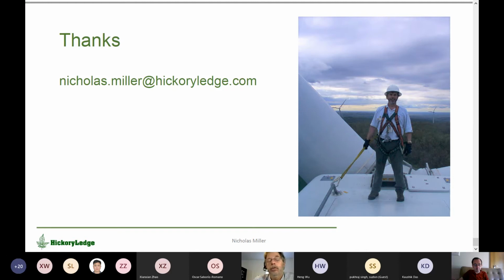So you can ask all sorts of questions, like, should H be situationally dependent on operating condition? Does it need to be symmetric? Should H be a big number on the way up and a small number on the way down? I can do all sorts of stuff. So you've got a bunch of knobs to play with, even if you want to stick with the synchronous machine equation. So why do I keep saying don't just mimic?